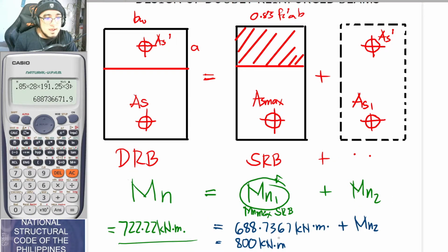But take note that you must resolve for this using singly reinforced beam design, because what we solved here is the maximum. So we would reduce it, reducing its As now. But since our video here is concerned with doubly reinforced concrete, of course we would be designing it as doubly reinforced concrete.